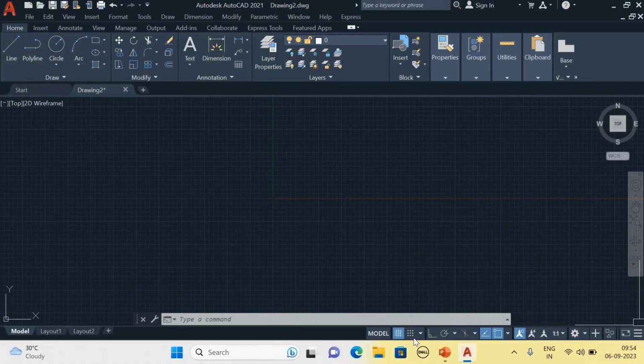It includes options such as ISO draft, ortho mode, auto snap or snap, etc. Here you can see different options are given. Suppose here, see, ortho mode, the shortcut for that is F8. If you want to draw a line straight, you have to turn on ortho mode. Another option is given, polar tracking option, ISO draft. Okay, so this is called the status bar. Is that okay, all of you?